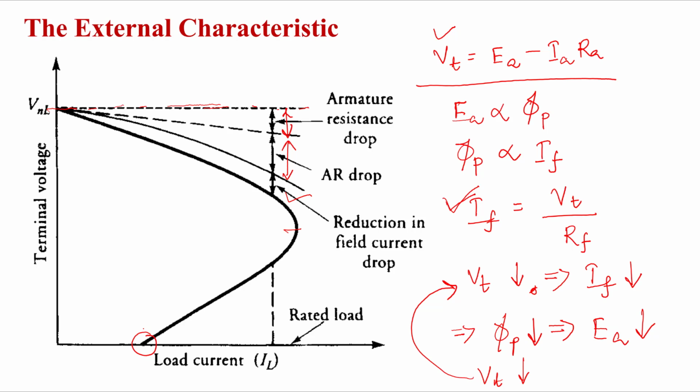If the machine is operating in the saturation region, the voltage is stable; if the machine is operating in the linear region, then we cannot control the voltage, it will drop down suddenly to zero. Therefore, we should remember this point: the shunt connected self-excited DC generator should be operated in the saturation zone. It should not be operated in the linear region, right?